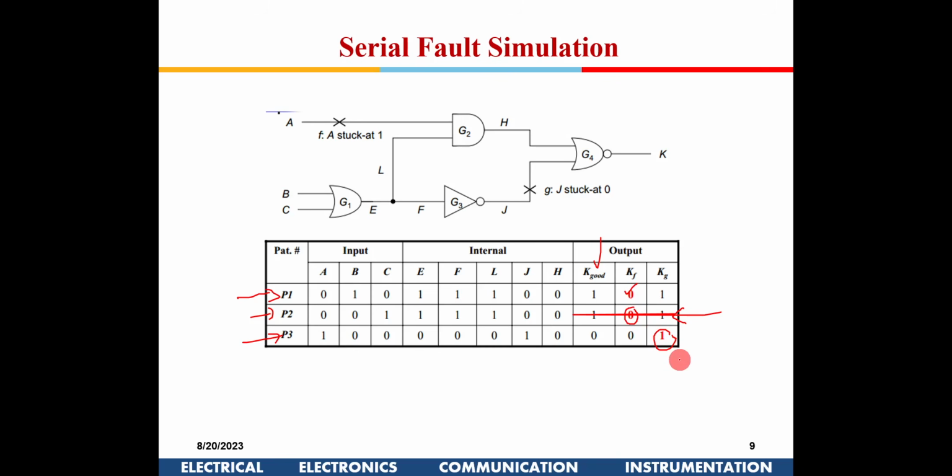Okay, if you don't do fault dropping, then this will keep repeating like this. So both options are available. If you drop the faults, then it will save time in generation, right? If you don't do fault dropping and then later on you try to maximize that, in that case you might land up in having a lesser number of test vectors.